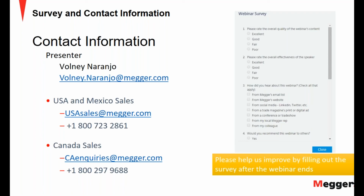You do have 1679.1, which is basically a guide to lithium-ion batteries. And typically, when you're dealing with lithium-ion batteries, they're going to have what's known as a BMS on them. They'll have a battery management system embedded in them, and they'll also have a battery monitoring system on it. Most of these lithium-ion applications are in energy storage, so they're seeing a cyclic application. They're being discharged and recharged periodically, pretty much on a daily basis.